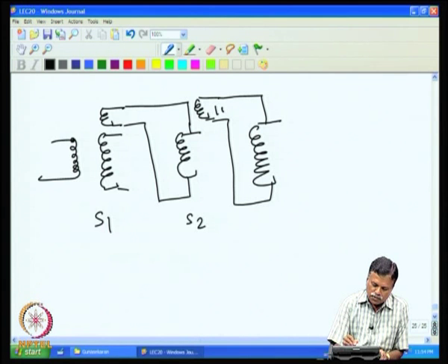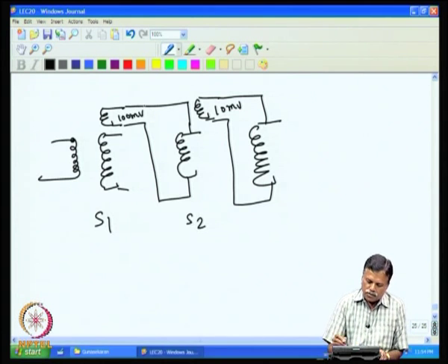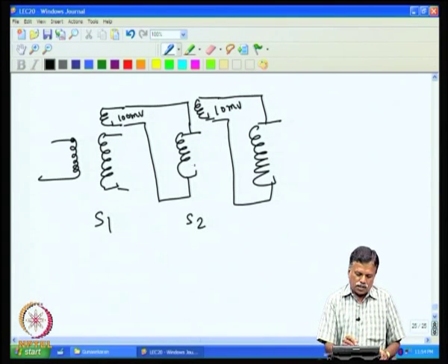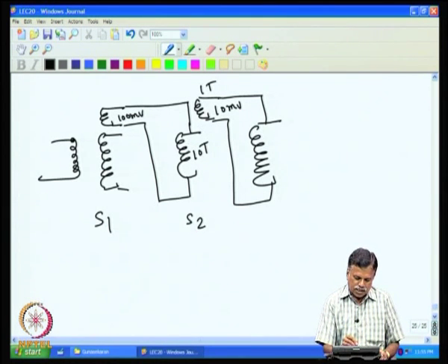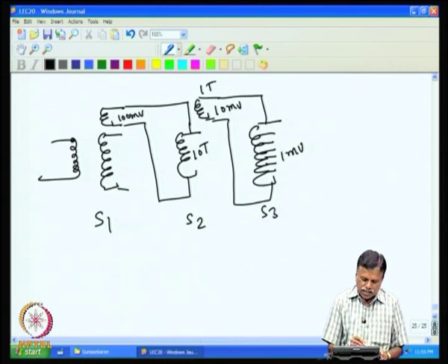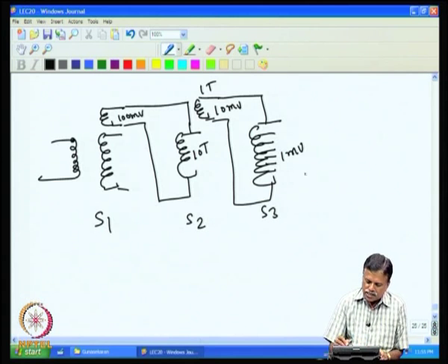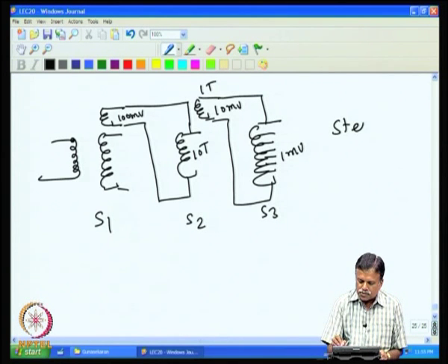So, this is 10 millivolt, this is 100 millivolt, because this has 10 tenths and this has only 1/10. So, 1/10 of this voltage is coming here. So, 100 millivolt is across this. So, you will get 10 millivolt, and now there are 10 tenths, so each one is having 1 millivolt. So, the step size of S3 is equal to 1 millivolt.